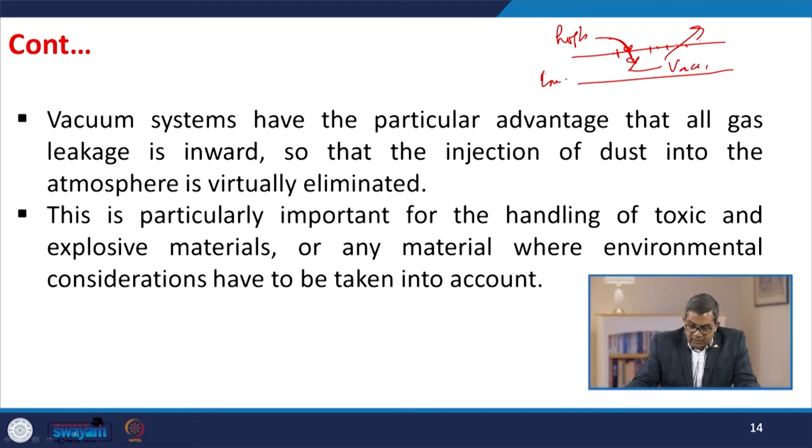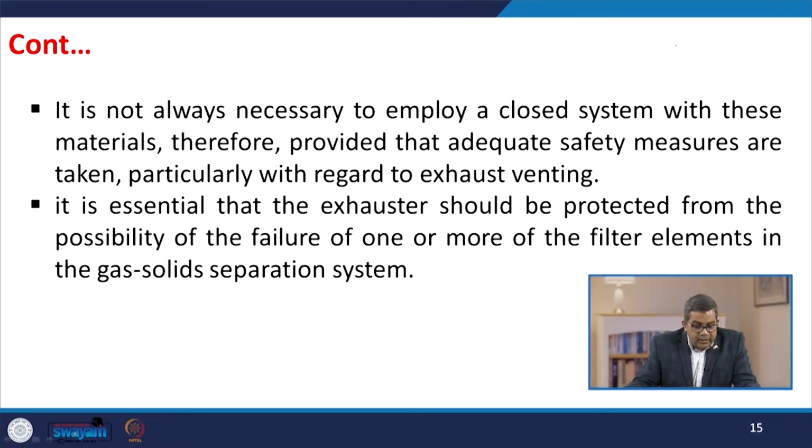This is important for the handling of toxic and explosive material, or any material where environmental challenges have to be taken into consideration. It is not always necessary to employ a closed system with these materials, provided that adequate safety measures are taken, particularly with regard to the exhaust venting. It is also essential that the exhauster be protected from the possibility of failure of one or more filter elements in the gas solid separation system.